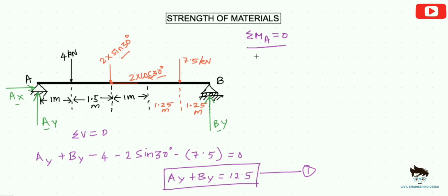Okay, coming back, what is easy about this? It is easy because we know that neither simple support nor roller support can produce a moment, which means moment at point A and point B is 0. Correct? We can consider either of the points, we will end up getting the same result.